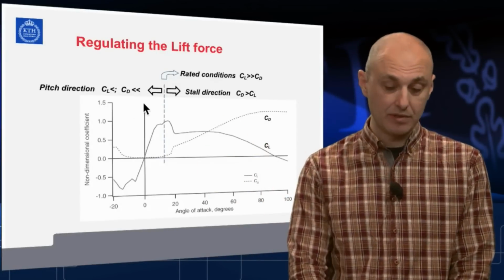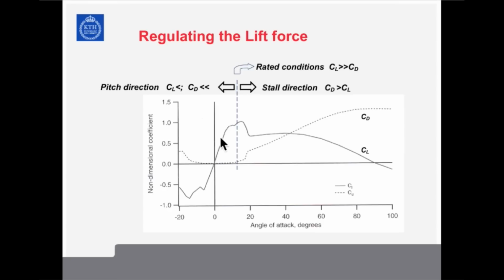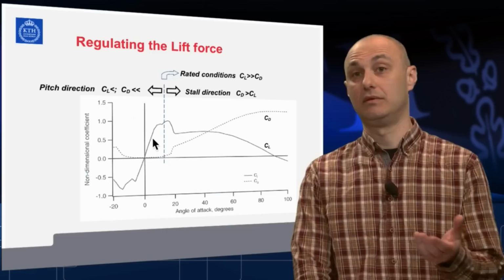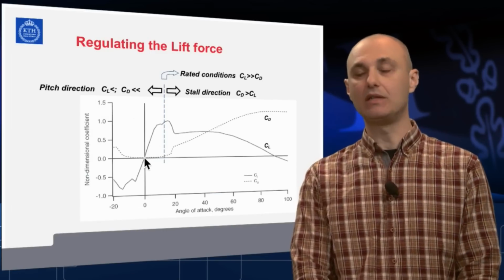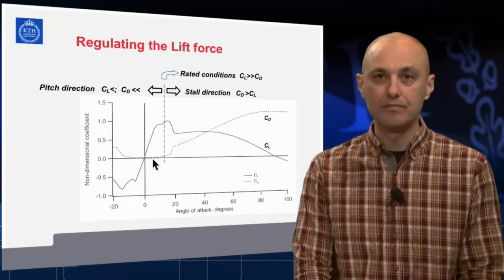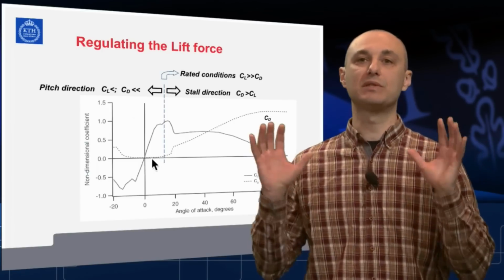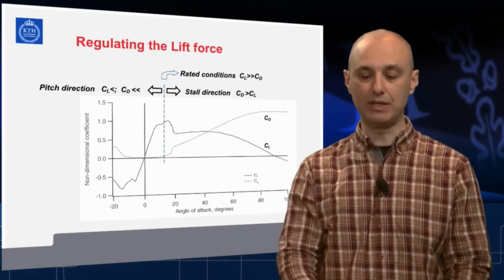The pitch regulation would attempt to keep low angles of attack and then decrease the lift, going towards the zero angle of attack if necessary, and mechanically the turbine should be able to do that. This is the way to stop it, while drag is also maintained low. So you do not produce enormous thrust load pushing the machine.